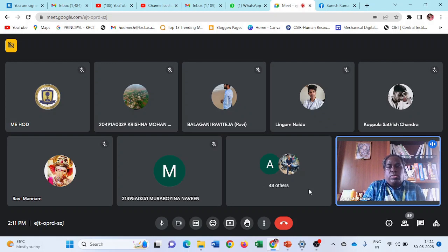And also the drill tool, the quill, also joins with this hub. So the hub is one of the main components in a mechanical assembly. For producing this hub, we can produce two steps, step number one and step number two. Not only the external step, we may produce it with the center lathe. After that, inside of it you may see two holes available.